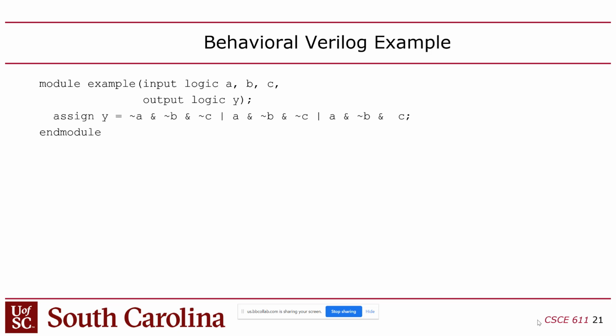And that's because Verilog has this kind of shorthand where if you have a type and then you specify multiple symbols after that type declaration separated by commas, each one of those will inherit it. So obviously A, B, and C are inputs, right? Because I needed to make Y an output, I had to break up that sequence of A, B, C and create another type, output logic Y, right?